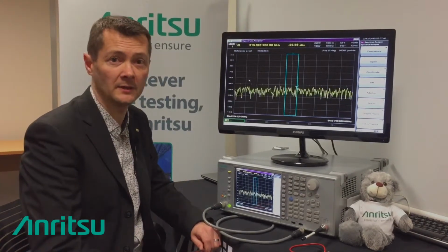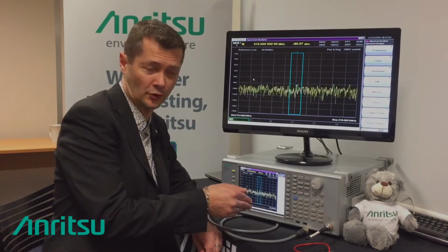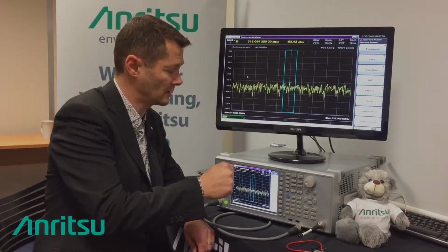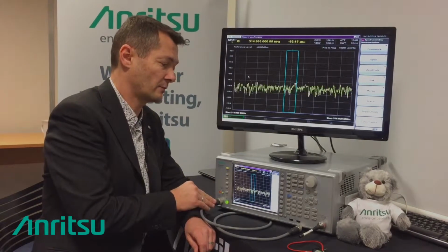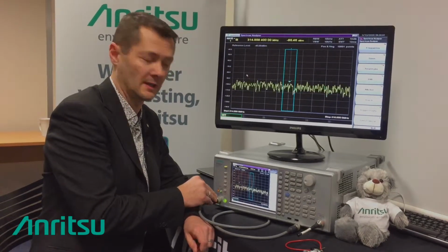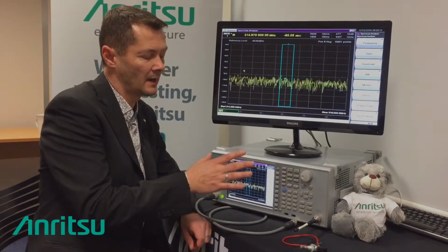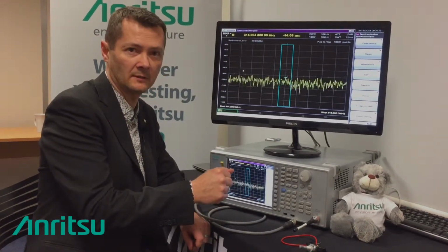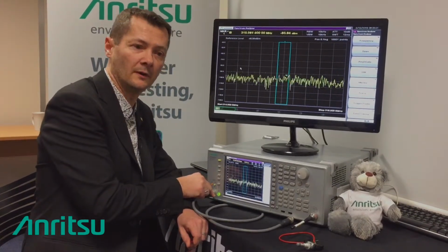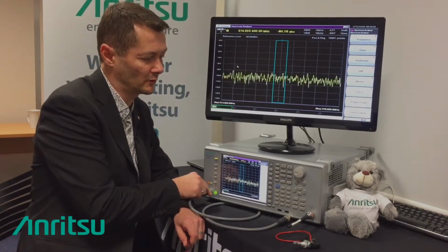In this MS2840 VSA unit, we have the advantage of having a few different functions. One is the spectrum analyzer that we see at the moment. One is the VSA function. And the advantage of such a platform is that on RF models we can have the built-in VSG. So this demonstration will focus on how I will digitize the signal that will be processed internally, converted internally, and output on the VSG to be replayed physically. This is what I will try to demonstrate at the moment.